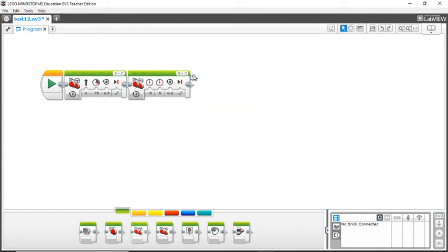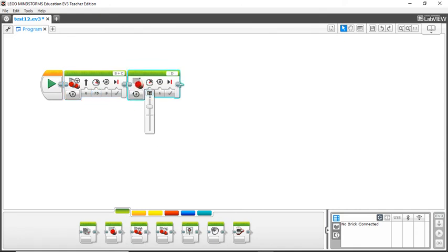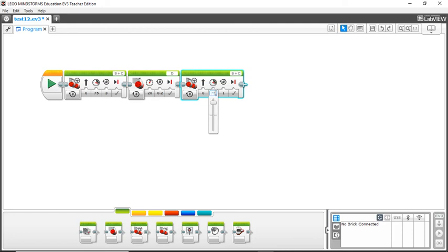So let's erase these. Let's say you want to swing an arm or something on your attachment. So let's see, drive forward, 3 rotations, 75% power. You swing your arm. Let's go 20% power, swing your arm, 0.2 rotations, and then let's say you want to go back to base. So you drive out of base 3 rotations, you swing an attachment, and then you want to go backwards. All you have to do is type in 75% power, and then go back negative 3 rotations. So that'll bring you back. That's pretty basic on the coding of that.